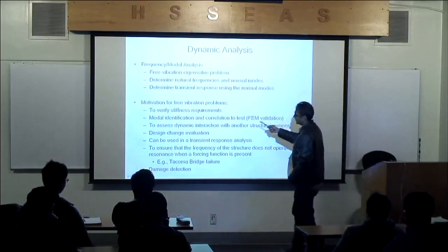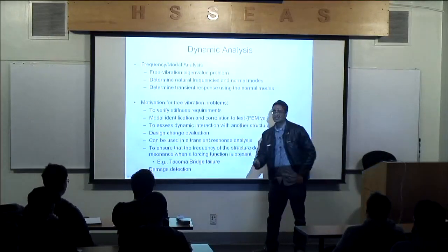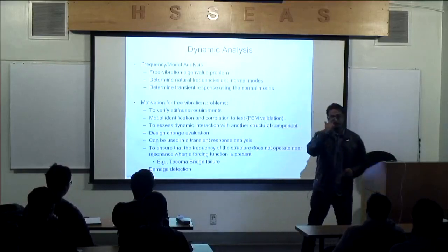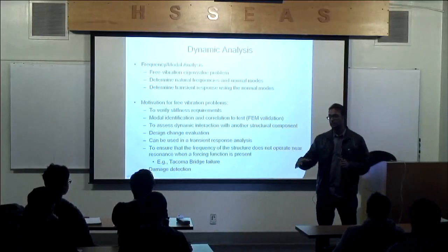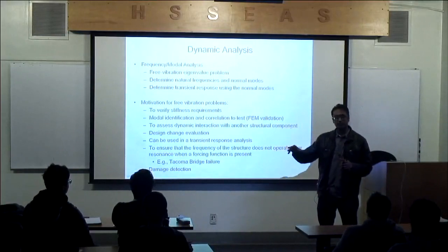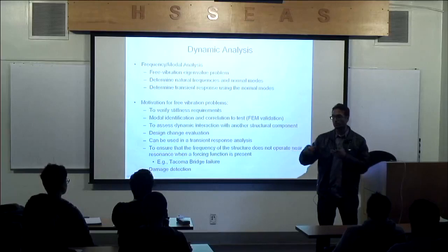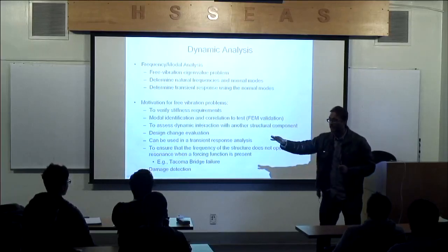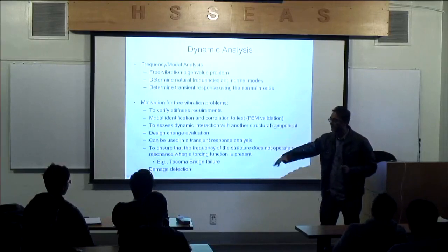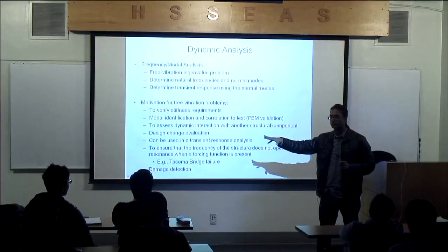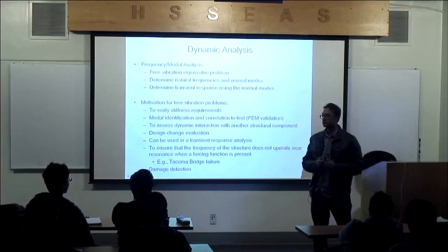We can also use it for damage detection. Say that I have a wing, and that wing has particular mode shapes and frequencies. If I induce damage to that wing, because maybe something happened to it, and now I calculate the modes and frequencies of that wing, well, maybe the modes and frequencies will now be different because there's damage.